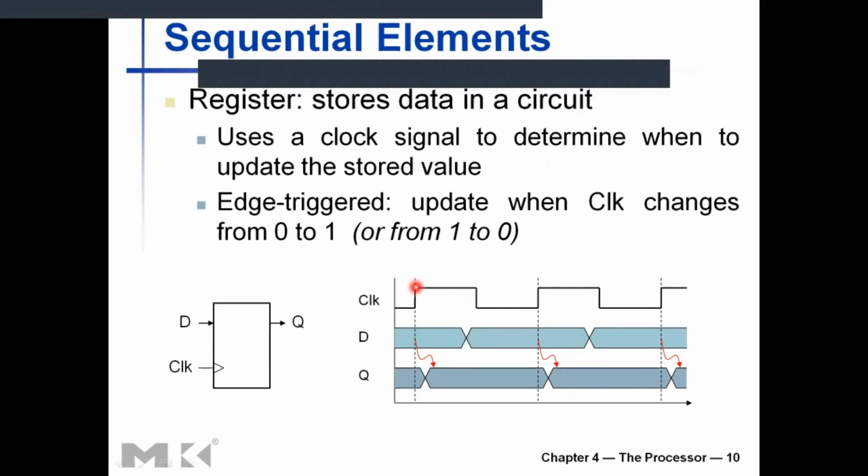In the clock signal here, the sequential element can be triggered on edges like this, a transition from logic 0 to logic 1 or logic 1 to logic 0. In this case, we are taking the rising edge, from 0 to 1, right? At the rising edge, you take the D value, the input value, and the current state, and it's given into the next state.